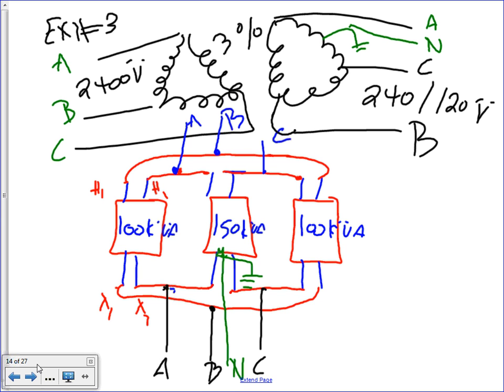Where would you use a system like this, guys? Lift stations, city lift stations, well houses. If we have a house with multiple wells to pump the water, the city water, and all of them are 240 three-phase, and only a couple of lights and a couple of receptacles in that house, very typically they have 240 three-phase center tap. So you use the 120 for the receptacles and the lights. Very typical. Would you feed a commercial industrial building from this system? No. This is a unique system for special application.